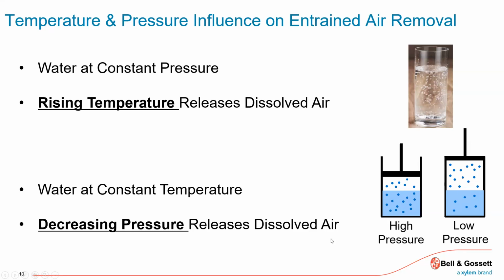Now make it 40, 50-degree water and make it 180-degree water or 190-degree water. You got a tremendous amount of air coming out of solution. So depending upon the temperature, the water can either absorb the air or it releases it. We want to catch it when we release it.